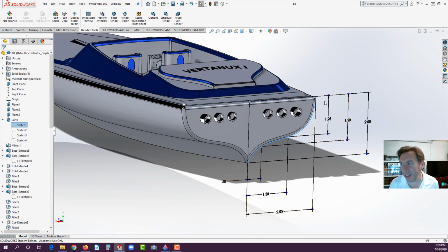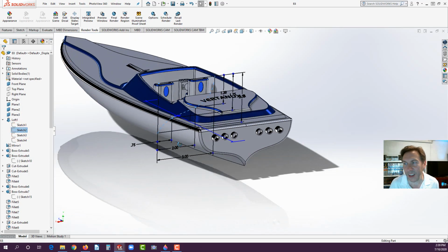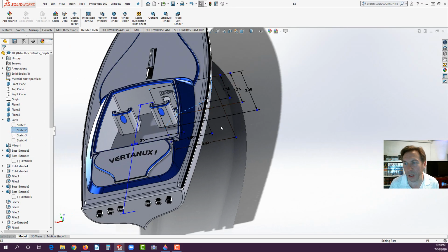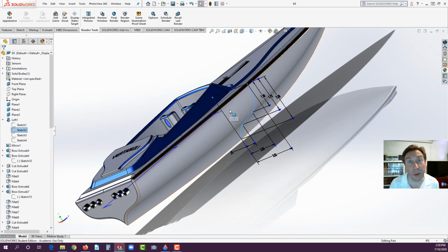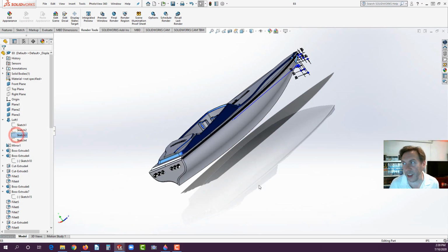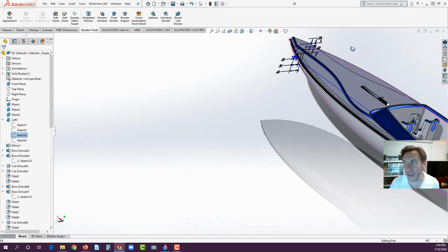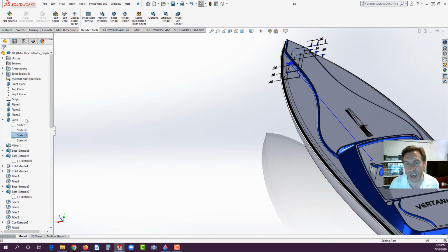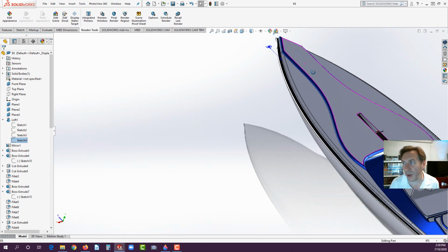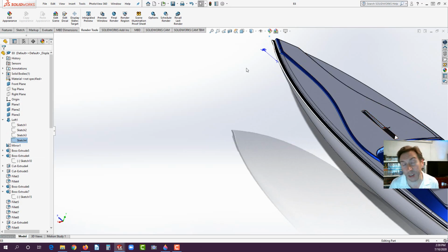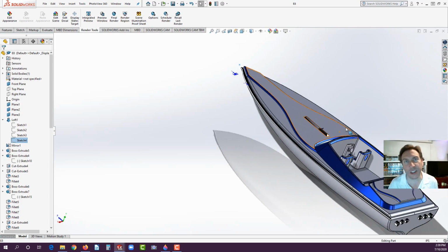We're going to create that backside with these dimensions. And then we're going to copy it and enlarge it as it goes through onto a new plane. And that plane is going to be offset a specific distance. And then another one will offset, as you can see here, about 8 inches. And then finally for the tip, we come off 1 inch and we put a little point on it. And then we could actually loft between those sections and then mirror it over to make the boat hull. So let's begin.